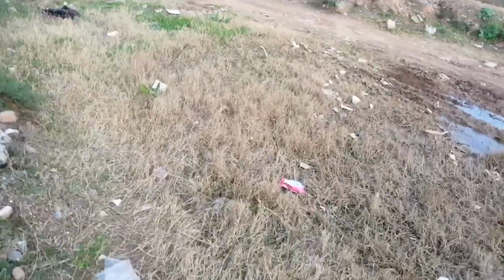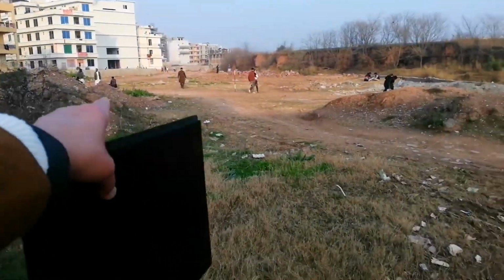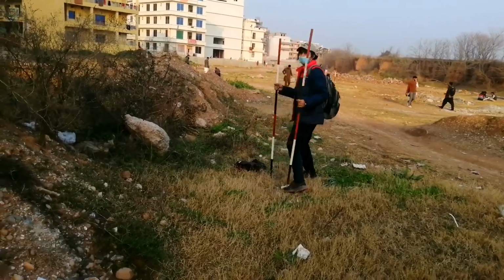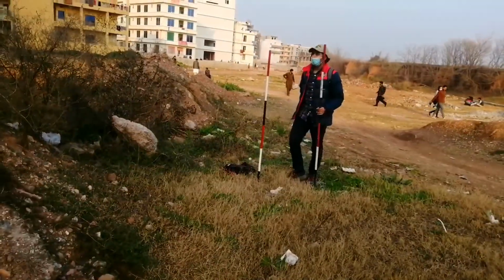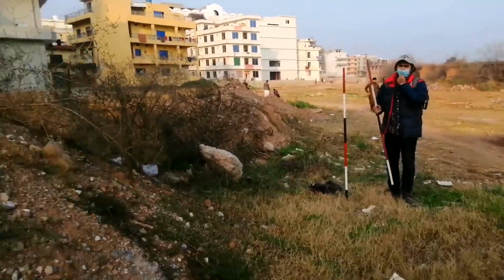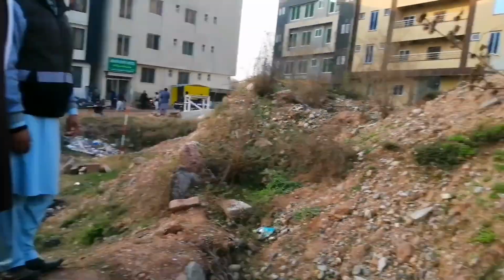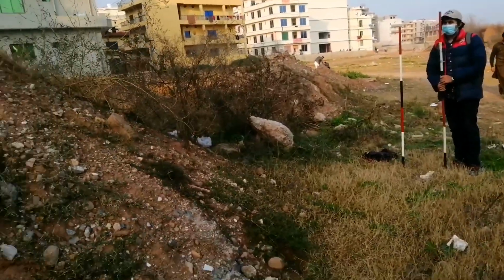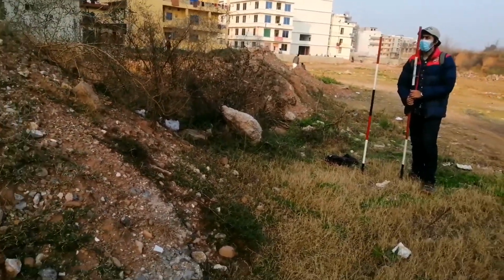As you can see, we are going to the other side of the heap, from where the point A is not visible. So this is the point we have chosen, and I have asked my student to place the rod there. So we have chosen this point B. So we need to range this point from the first point we have already chosen. So these are the 2 points you can see in this video, but they are not directly or mutually intervisible.